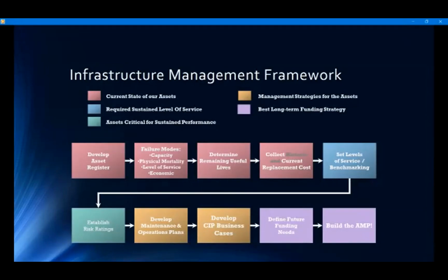So over the last decade, the district has implemented an asset management program within an asset management framework. This began with the development of an asset register to identify what our assets are and where they're physically located. We also began to identify failure modes, remaining useful life, and current and historic replacement costs for our assets. And this has allowed us to understand when we can expect our assets to fail and what the financial implications of those failures are.